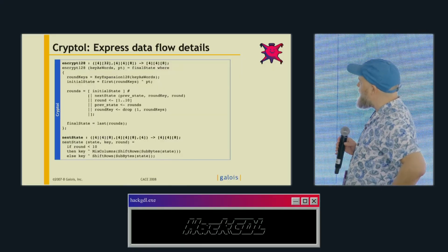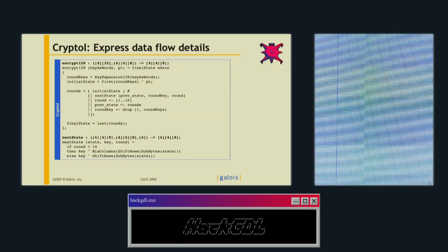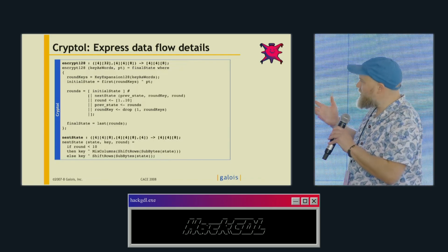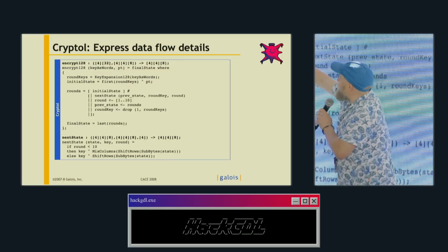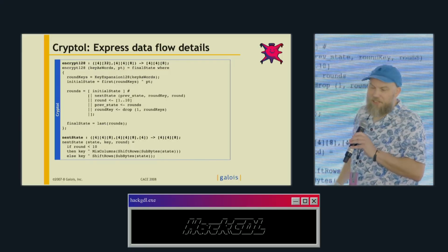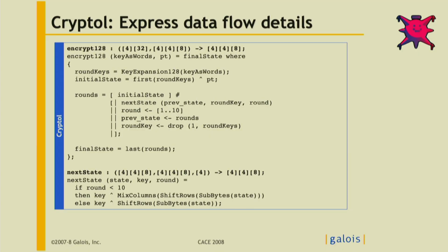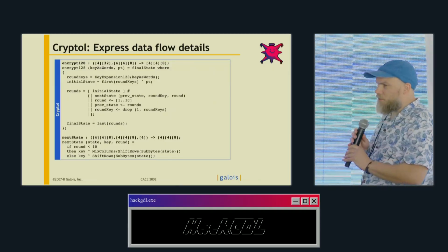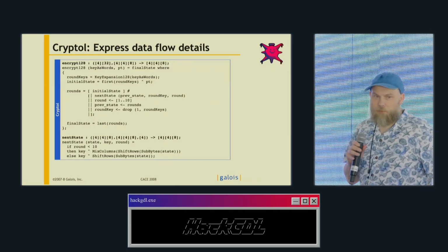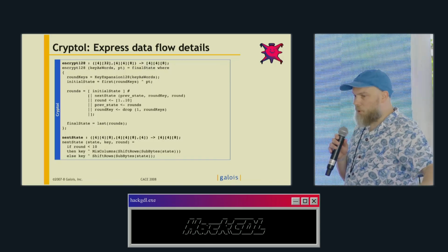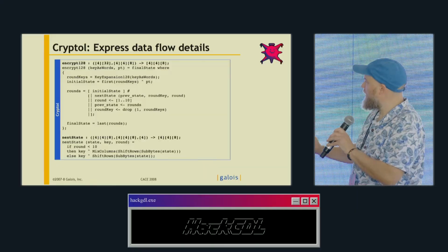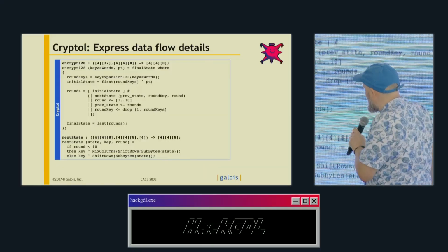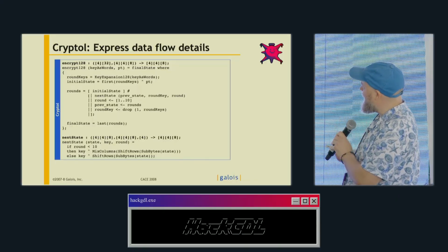Now, this is a very weird way of writing things, I admit, and it's a recursive value. We all know recursive functions, but recursive values are maybe not so common because most modern programming languages don't support them yet. But you're defining a constant, rounds, here, which occurs within the right-hand side of the definition. This is called a stream equation, because I'm referring back to the constant, but I'm putting something at the beginning of the stream. This is how you write things in Cryptol, in a slightly roundabout way, to make the synthesis in hardware easier, because hardware works really nicely with these kinds of equations. And in Cryptol you can translate this directly into a clocked circuit. Each clock cycle, it will generate another element. This kind of description facilitates that translation.